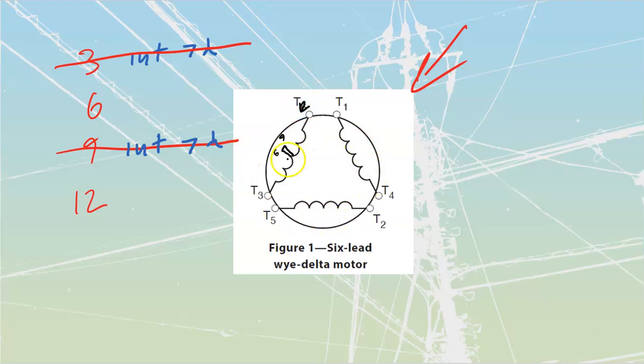So I would have terminals 3 through 6, 9 through 12, etc. off of here, and I could be either seriesing those or paralleling them depending upon what the voltage is. That's just 3-phase motor connections based upon the supply system we would be looking at. What we're looking at over here is just the simplest one, so you can apply that to a 12-lead if you need to.